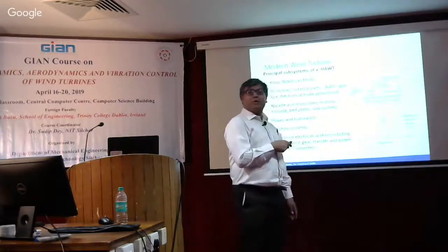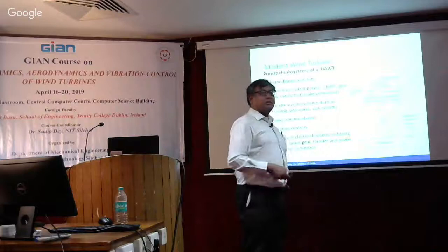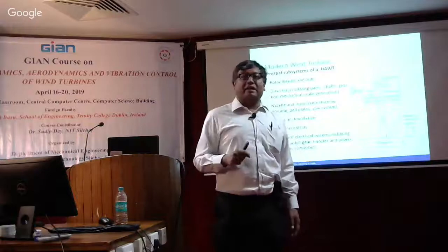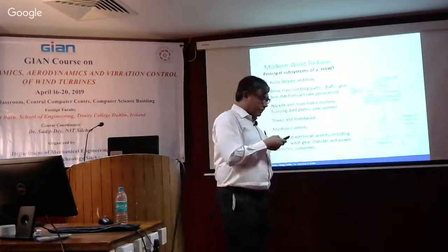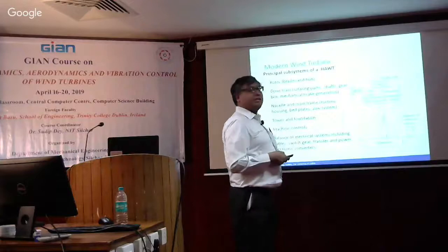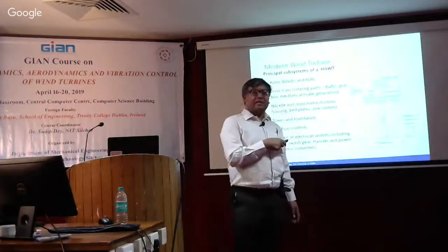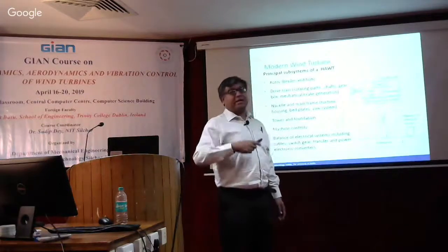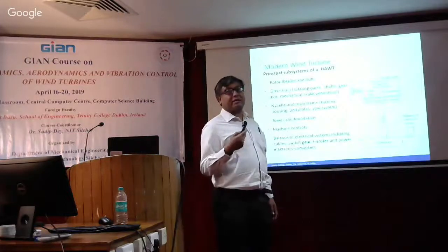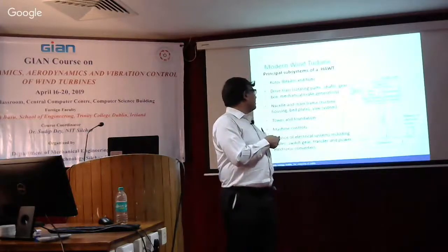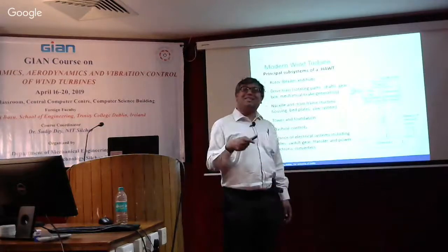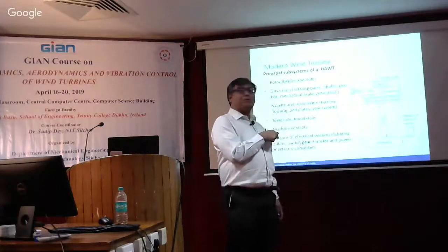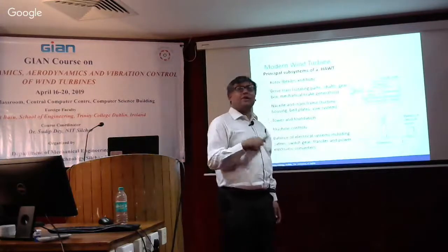But again, from the downtime point of view, there is a downtime. We were discussing downtime and the requirement to actually be connected to the grid, but the downtime is not very high. Whereas if you have, for example, a blade damaged, that doesn't happen that often. But if it does get damaged, then the cost is enormous, because a replacement of the blade could be a huge amount of time and effort and so on. And obviously, replacing is not easy, whereas a gearbox is much more easily replaced than a blade. So damage in a blade is less frequent, but the effect is far more significant.